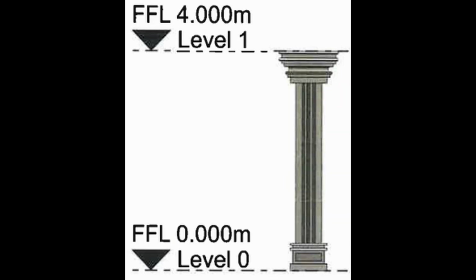Openings, cuts, and voids. Hosted families can cut openings in their hosts. There are two methods. Opening cuts always cut the full thickness of the host. Void forms are more flexible, but cannot coexist with opening cuts in the same family. Void forms are not recognized by copy/monitor, which can lead to coordination issues. For this reason, best practice is to use copy/monitor only for levels and grids, reference planes, and swapping components. Inside a family, reference planes define the left, right, top, bottom, and center of the object.